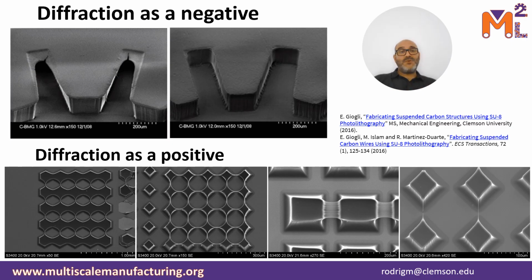Now during the post-exposure bake, well, this is more about the exposure actually. So when you're doing the exposure, you can imagine that you will suffer from diffraction, right? Especially if you don't have a very close contact between the photoresist and your mask. Most of the time, we do not want that diffraction to happen, because then it can lead to something sometimes called T-topping, where you actually have cross-linked material on the top, and that will affect your resolution, right?